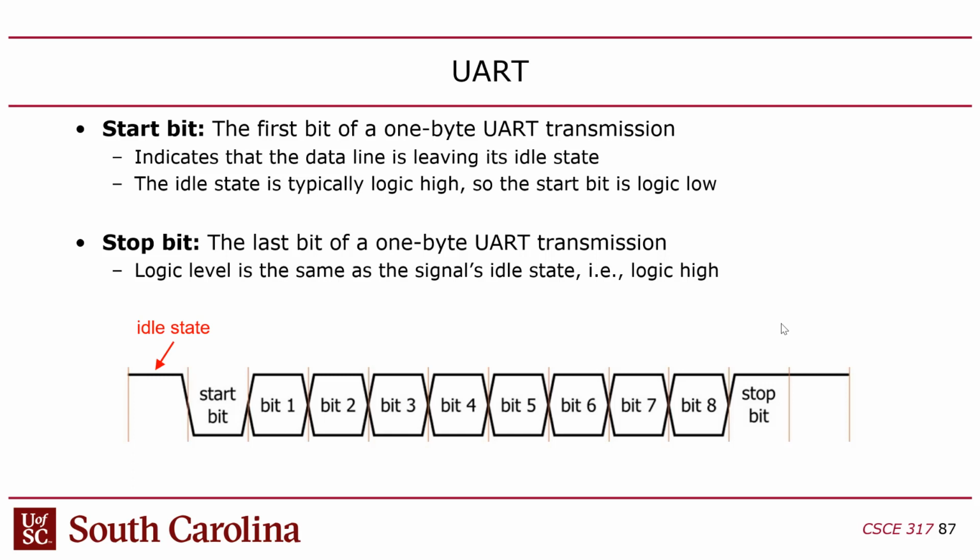For that reason, UART channels typically run slower than SPI. They run very slow, usually on the order of kilobits per second. And that's okay because UART is generally used just for textual consoles. So it's not a big deal that it runs slow, but by running it slow, you minimize the chance that the receiver will go into metastability by just happening to sample the data when it's transitioning, although it does happen. And there's a way to deal with that, which we'll talk about in a moment.